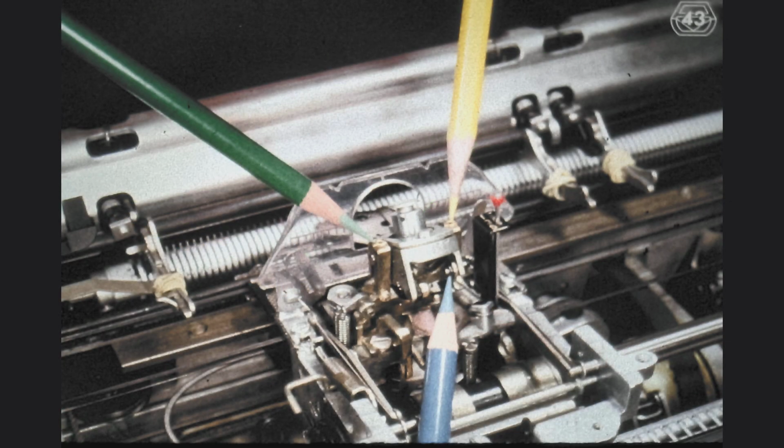In order to properly see the components and the position of the rotate detent underneath the tilt ring, let us now remove the tilt ring from the yoke, the two arms which support the ring. We remove the tilt ring by loosening the screws indicated by the green and yellow pencils and by removing the retainer and the link indicated by the blue pencil. In some older models, you might find that on the tilt ring, at the point indicated by the green and yellow pencils, you have a pin which can be extracted once you have removed the retainer. Be sure not to lose the pin.